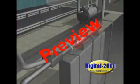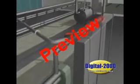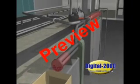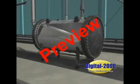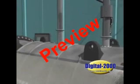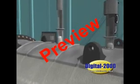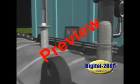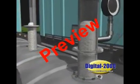On the afternoon before the accident, operators began to start up the process. But there was a mechanical failure in the extruder. While the operators tried unsuccessfully to fix the extruder, the hot plastic continued flowing into the waste tank for an unusually long time. Supervisors eventually aborted the startup, but by then the waste tank had already overfilled with molten plastic. The excess plastic clogged the vent line and the emergency pressure relief line.